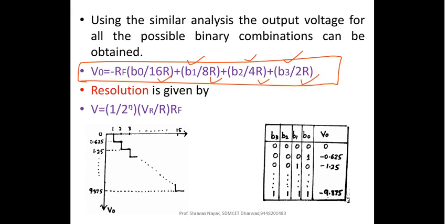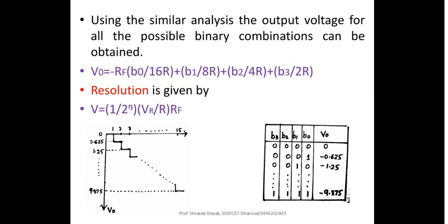So this is only for a 16-bit DAC. As the bits change, this also is going to change. This is not the general equation. This is the specific equation for a 16-bit DAC. Now depending upon whether a particular bit is connected to logic high or logic low, you can either include it or exclude it, right? And you are going to get the value of V naught.